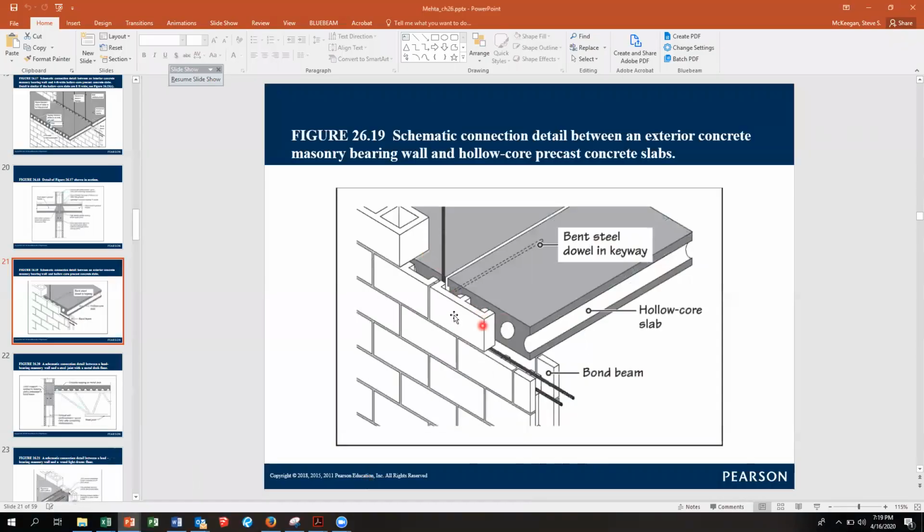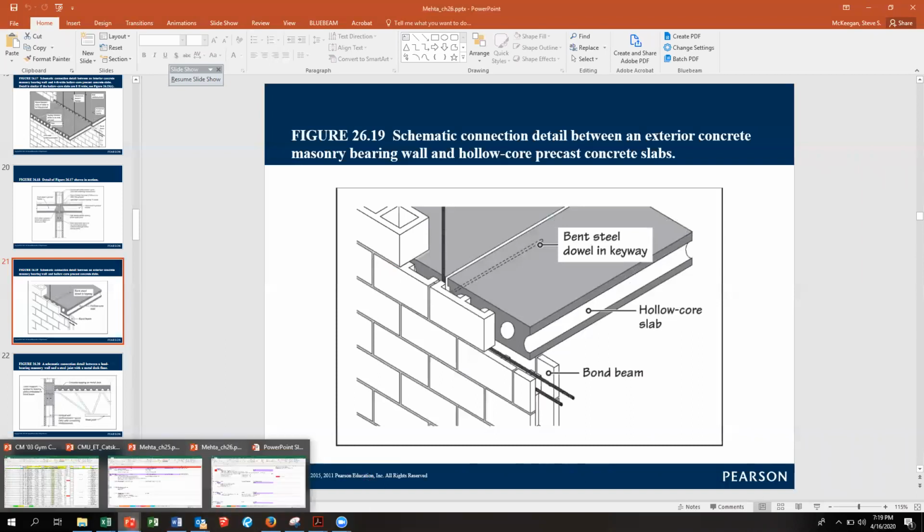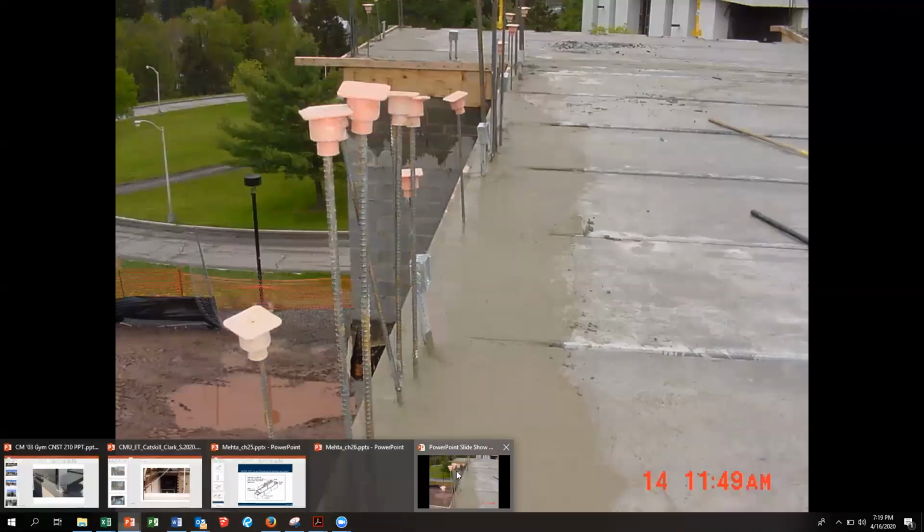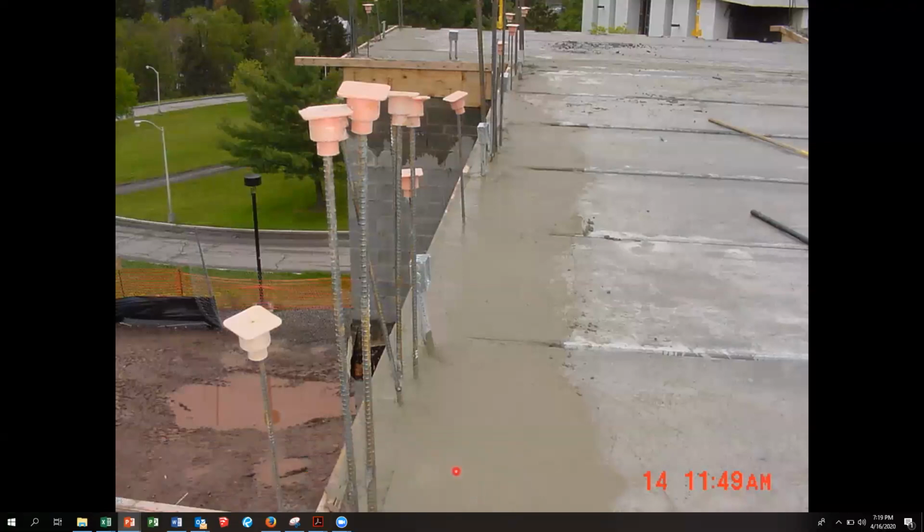So instead of this special cut block right there, they're going to grout that in because they have formwork. Once that's all ready to go, then you just start laying block for the next floor. We went through about a 10-year period where they built a lot of new buildings. It was a blast. I got to see a lot of good construction. But look at all the stuff that has to go inside those cores, because there are the dowels running continuous from the foundation all the way up through those blocks. There's your outlets and so on.